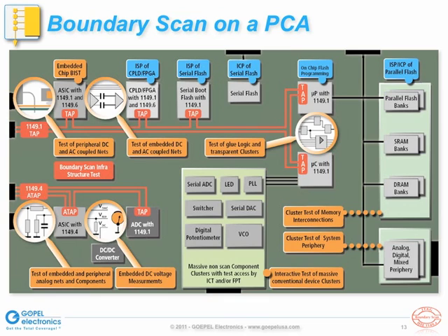Another type of test is the so-called logic cluster test. Logic clusters are digital functional blocks of non-boundary scan devices that can be stimulated and observed with boundary scan I/O pins connected to the cluster's input and output signals. Glue logic is one example of such clusters. Interface circuitry can be considered another type of cluster.